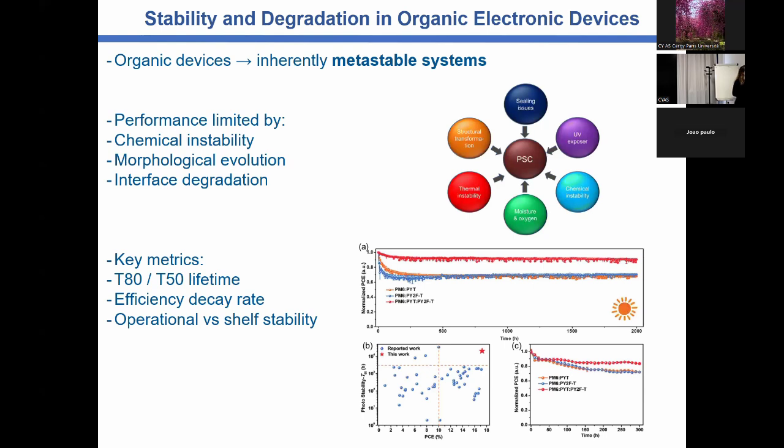And in terms of solar cells, we have these two kinds of measurements, also for OLED. It's quite important to see the efficiency over the time, because in organics we have these two different degradations. The first one, I will not talk too deep on this, but there is exponential degradation in the beginning that is usually with T80 lifetime, and then another degradation, which is more planar degradation.